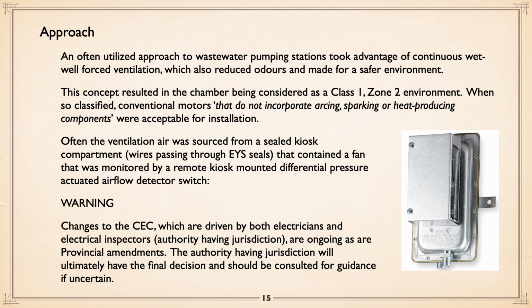Now, it depends on the electrical code for wherever you are. Some is insisting you have explosion proof motors, and we'll get into motors in a bit. You may find that they still exist. I think this is a good approach, but different people, different strokes. The ventilation air was classically sourced from the sealed kiosk compartment with seals going through an EYS that contained a fan that was monitored by a remote kiosk-mounted differential pressure switch. In other words, they basically wanted to know that an alarm would be fired if the ventilation system failed.